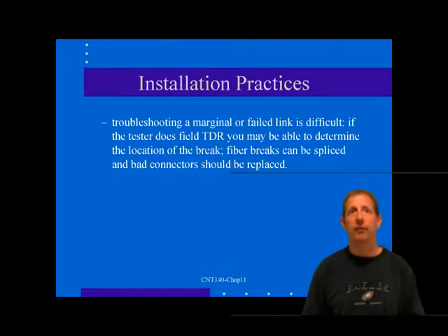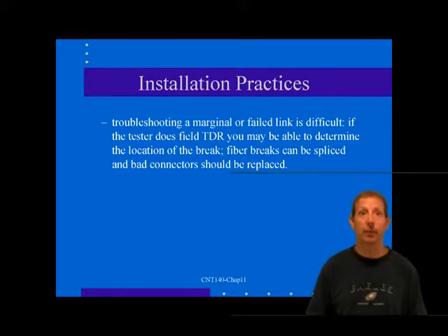Fiber breaks are permitted to be spliced because splices have inherently low loss. Bad connectors should simply be replaced, so be thankful that extra fiber was left at the point of termination.